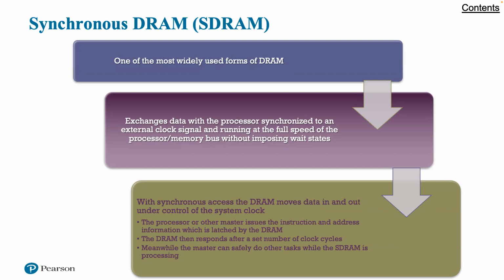In a typical DRAM, the processor presents addresses and control levels to the memory, indicating that a set of data at a particular location in memory should be either read from or written into the DRAM. After a delay, the access time, the DRAM either writes or reads the data. During the access time delay, the DRAM performs various internal functions, such as activating the high capacitance of the row and column lines, sensing the data, and routing the data out through the output buffers. The processor must simply wait through this delay, slowing system performance.